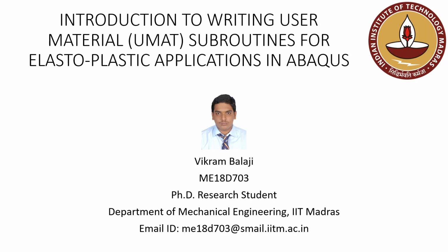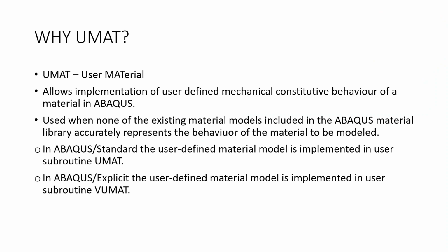So in this video we will be looking into some basics of UMAT subroutines, and we will also try to implement a very simple UMAT subroutine involving 3D isotropic linear elastic material behavior. So let us proceed. So why UMAT?